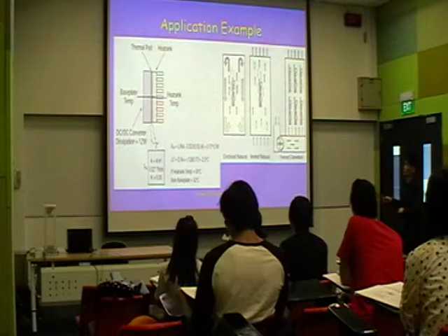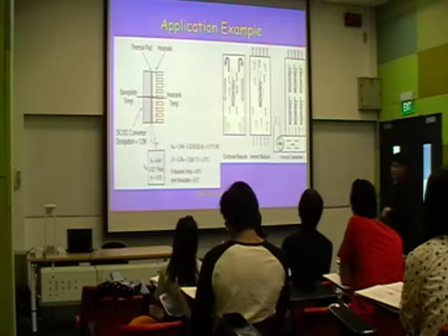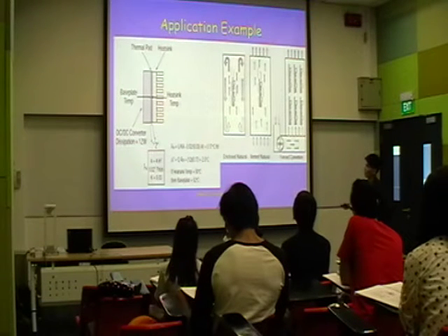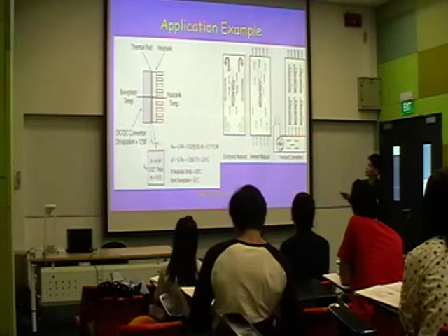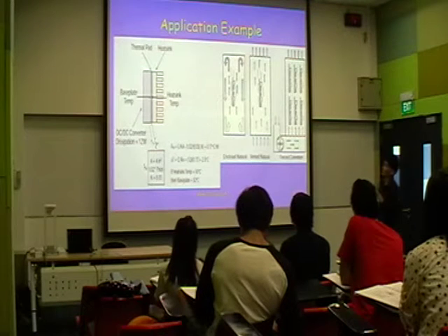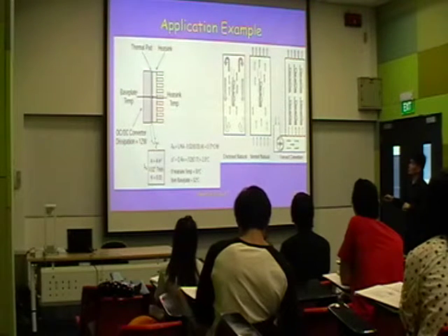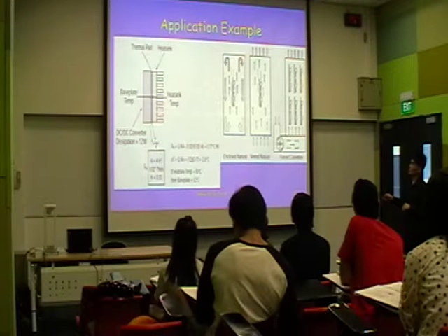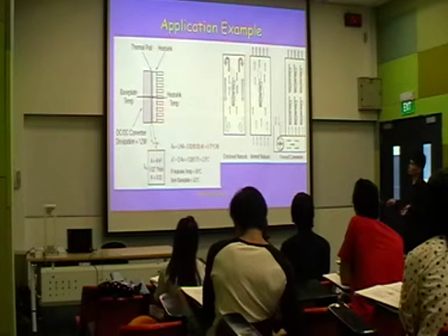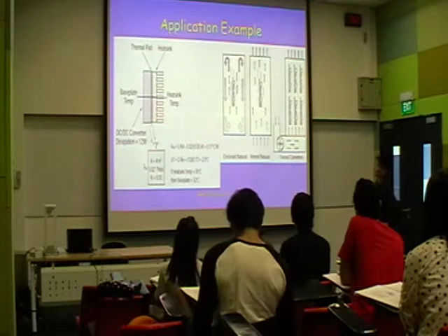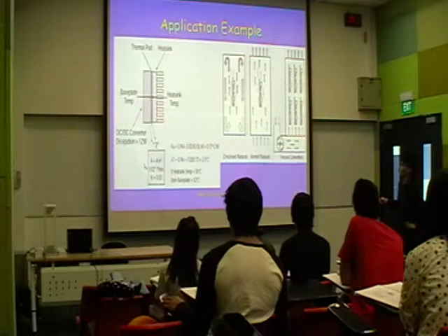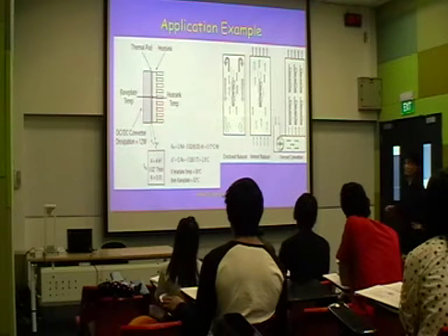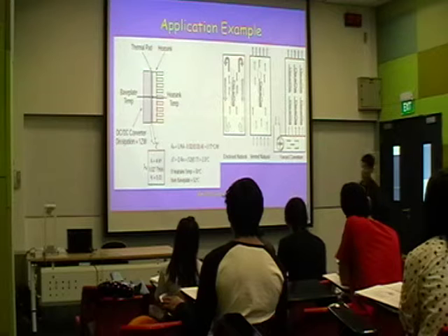So this one is just to give you some of the terms that the industry really uses. What is meant by so-called enclosed natural? All right, so there's no heat sink, but they just enclose it. Then ventilations. This one is not so ventilated. This one is more, there's a hole there to have the fresh air going in at one side, and the heat can be dissipated out from the other side. This one is more driven, like forced convection, where basically you use a fan. This one we use in the computer.